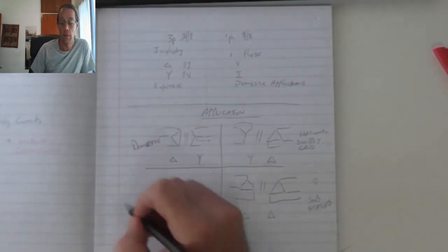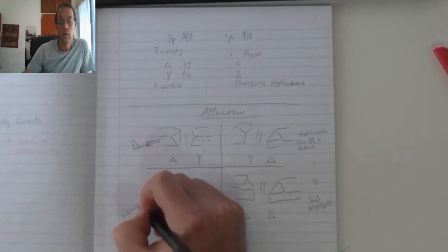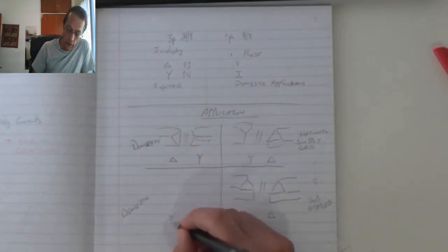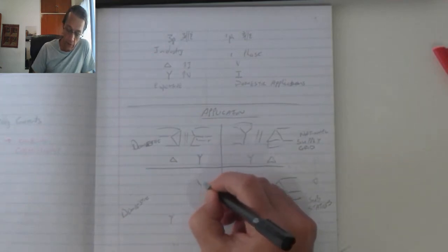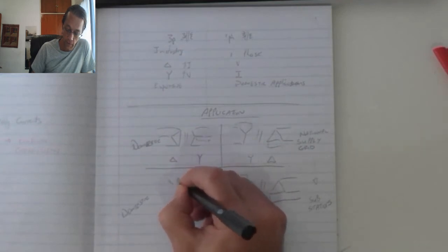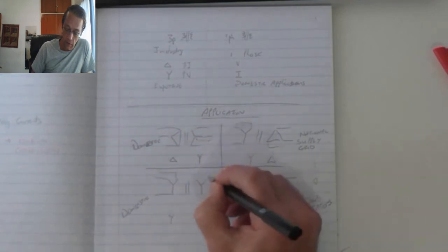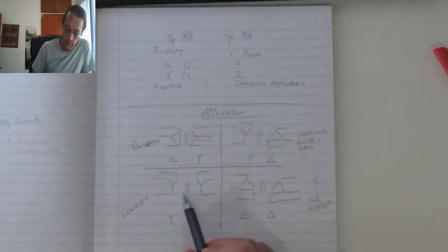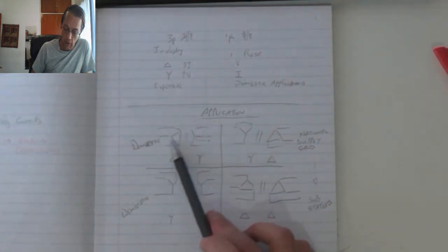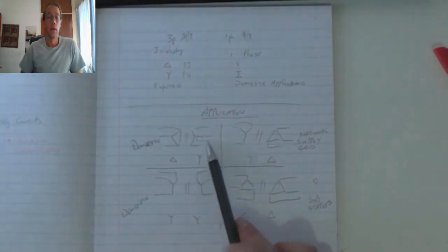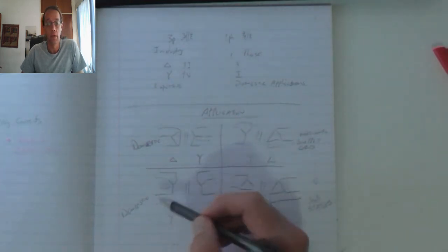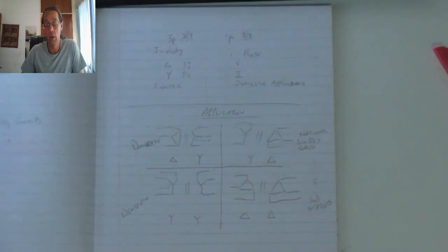And then finally, again on the domestic side, okay, we have the star-star configuration, where we've got our transformers connected in such a way that I've got 4 lines in and 4 lines out. This will typically be used after my delta-star configuration, because I've got 4 lines and 4 lines, and these are used for domestic, where we have our wiring into houses and factories.